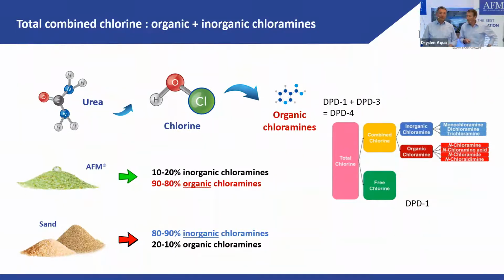They don't care. Just as a thought, for bioresistant filter media, you should measure monochloramine, which is easily done. DPD1 plus DPD2, and the difference is the monochloramine. And here you could set the level lower, 0.1 ppm, and we would always be in.